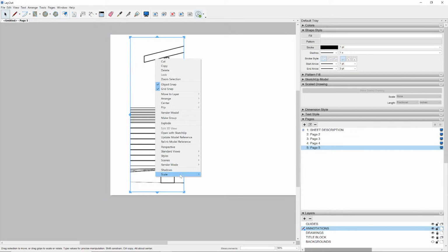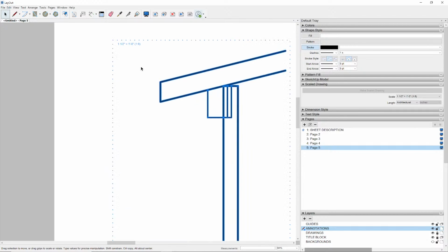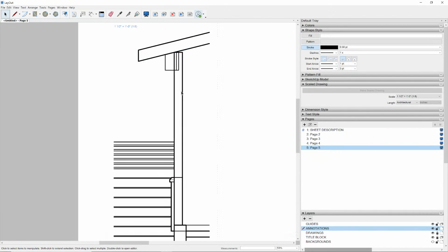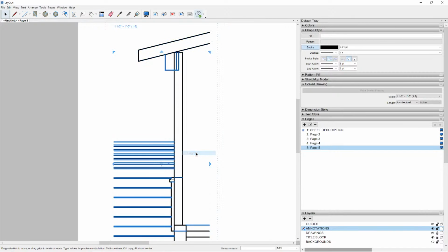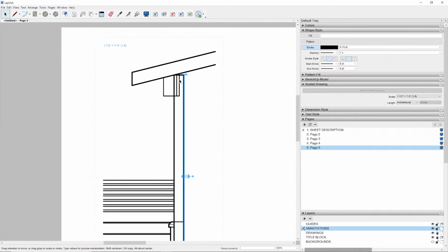So now when I explode it like this, it turns into a scaled drawing, so you get that scaled drawing up there. And now at this point, I can just go in here and typically I like to select all and ungroup. I like to just get it all broken down as far as it can go. And now you're just working with layout geometry.